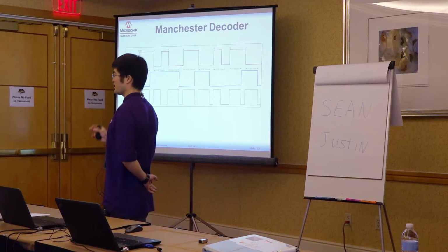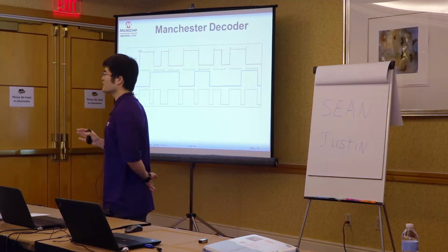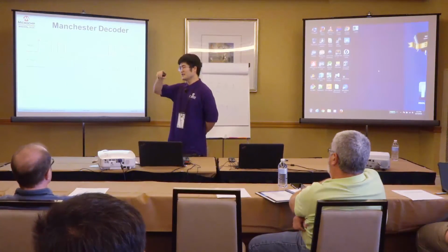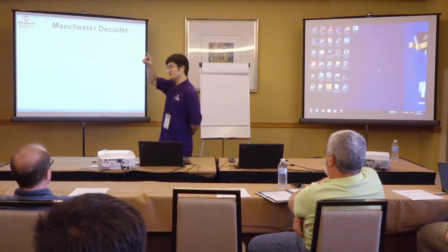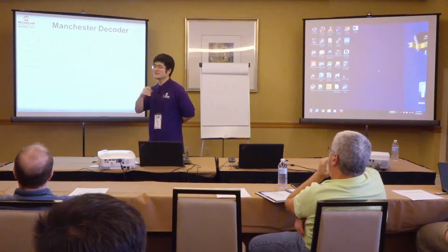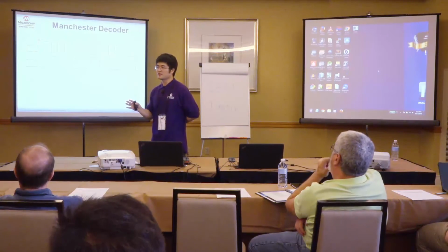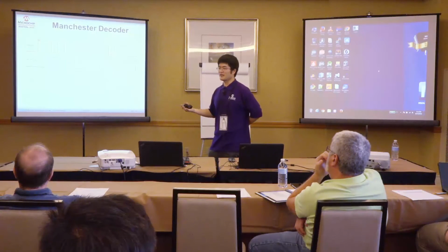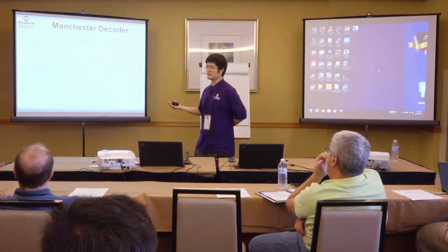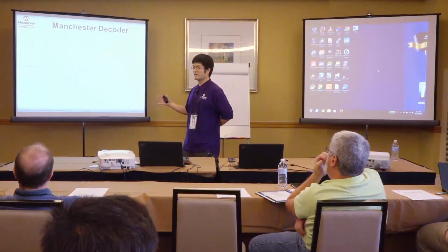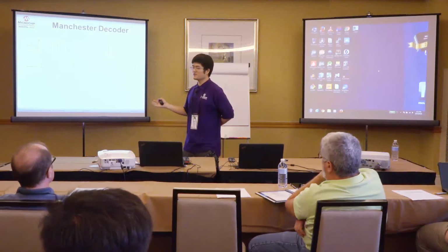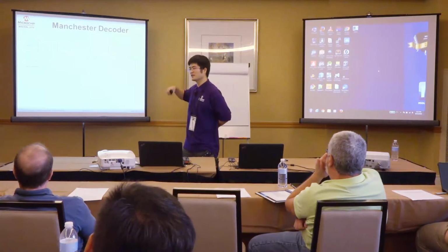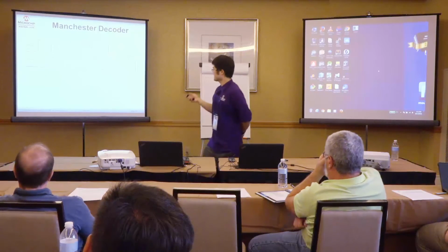I know the information about when the clock starts. I know where the first transition happens because that's embedded with the data, right? If it's 1, then it's a rising edge or falling edge. If it's 0, it's the other way around. So when the data comes out, the first transition I can always capture because it's by the definition of Manchester code, right? Make sense? So for the first bit, whether it's 1 or 0, I will always have that transition going on. Either it's rising or falling.